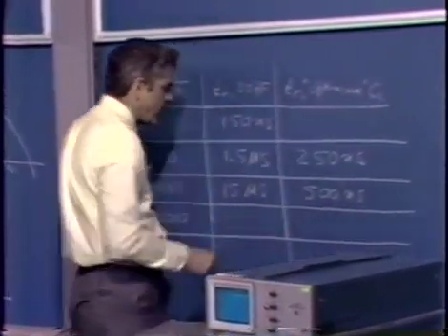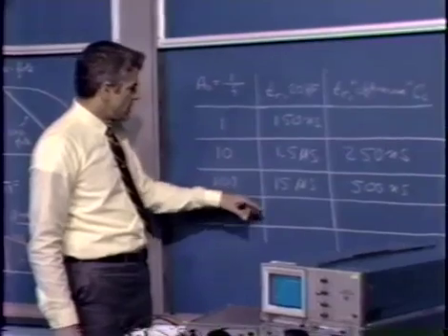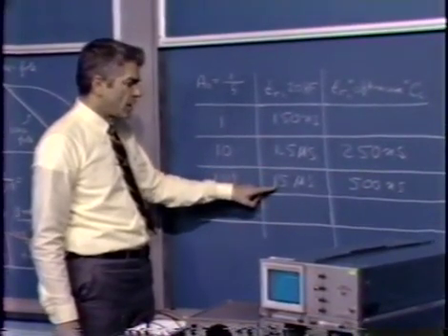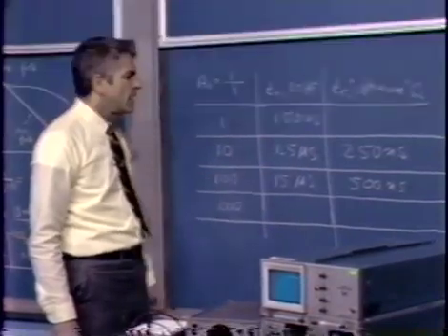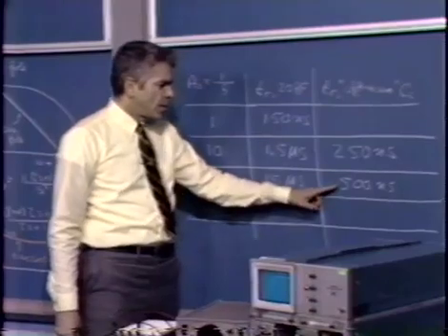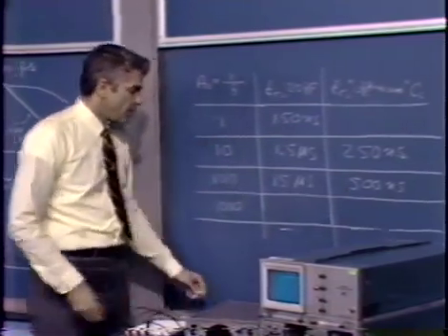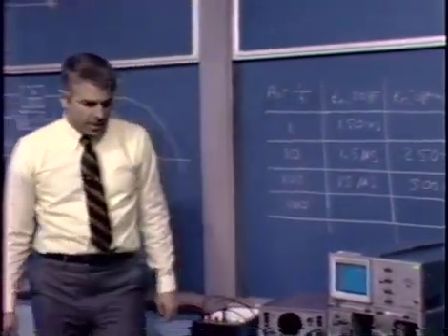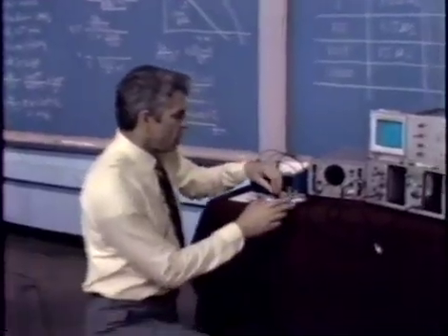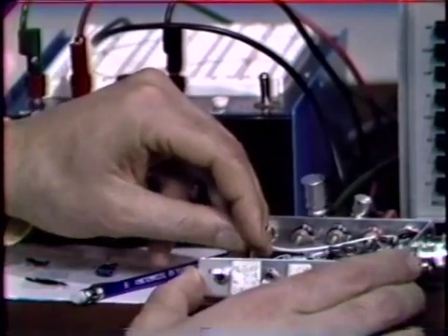but we're roughly a factor of 30 faster than the case that resulted when we used the capacitor that was selected for unity gain stability or for unity feedback. So we've made a very, very dramatic improvement in the bandwidth of the amplifier by simply choosing the compensating capacitor as a function of the closed-loop gain. Finally, let me go back to the original value, the 20 picofarad compensating capacitor, one last time.